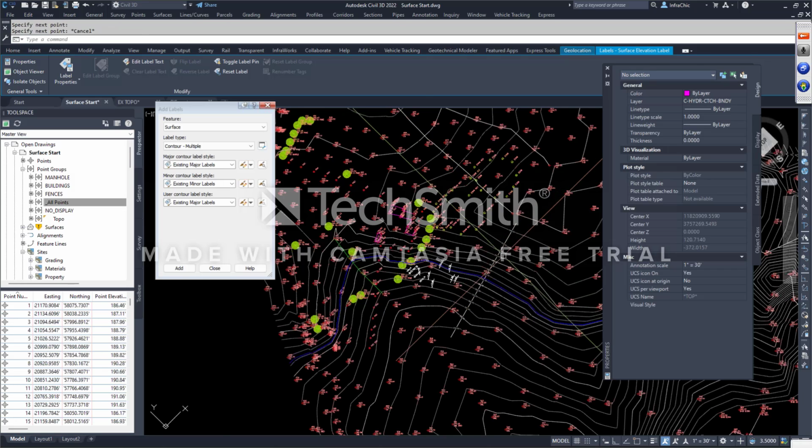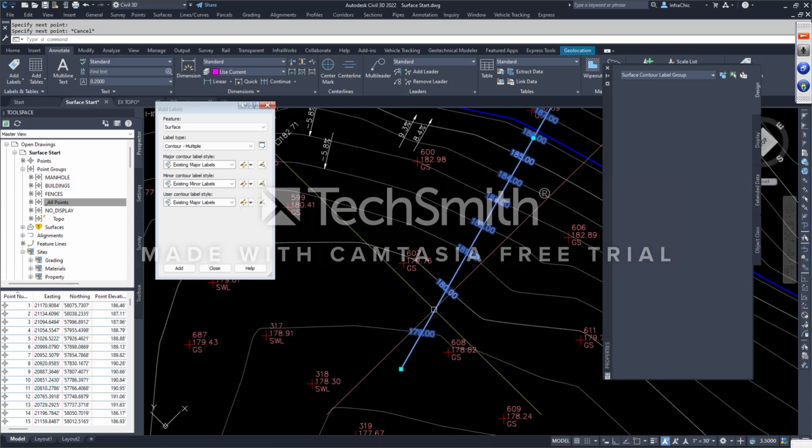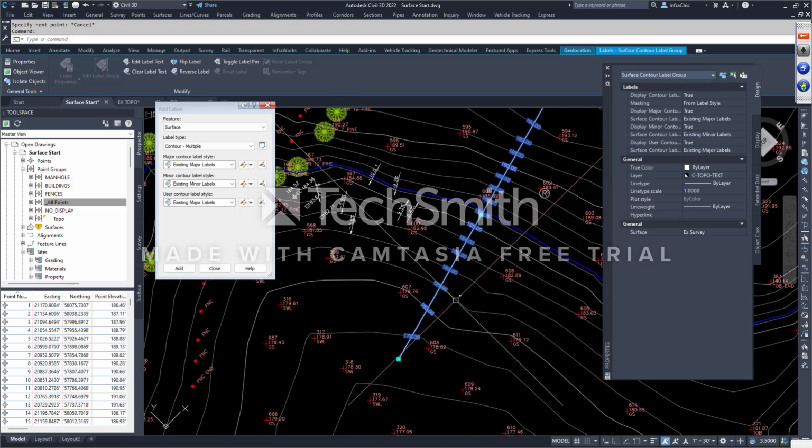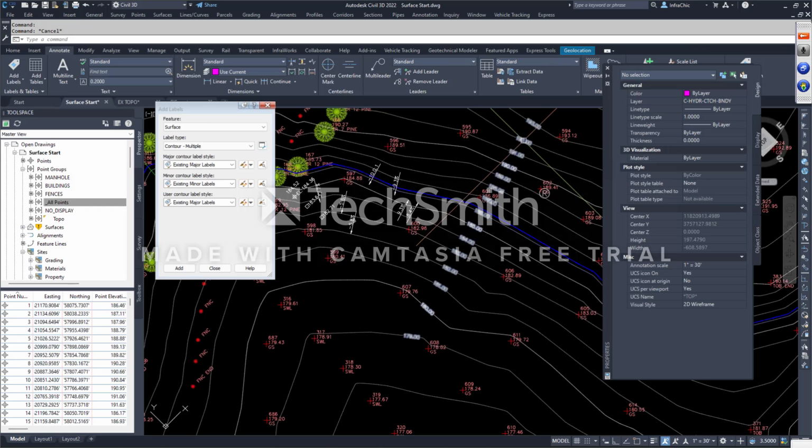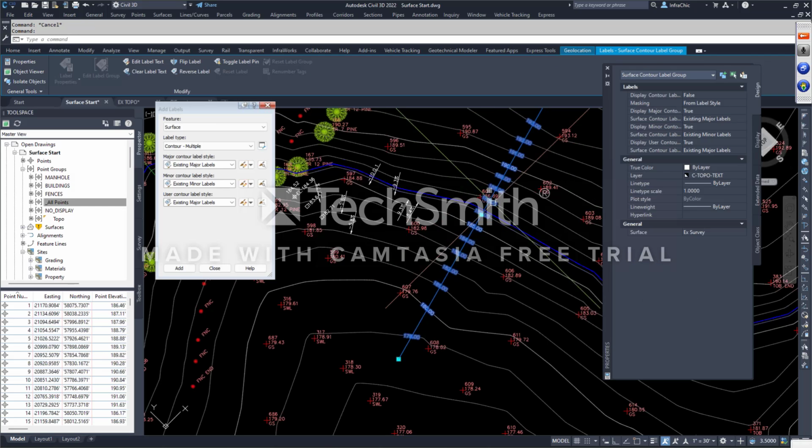Okay. Things to note about contouring. Anywhere the contour crosses this line, it's going to put a label. If the display contour label line is set to true, it will print. And it will drive your engineer and surveyor nuts. Turn this to false. When you do so, the line is still there, but it turns blue. When you hit escape, it disappears. When you grab any of the labels, any one of them, it comes back. Okay, don't freak out. It is blue, that's good.